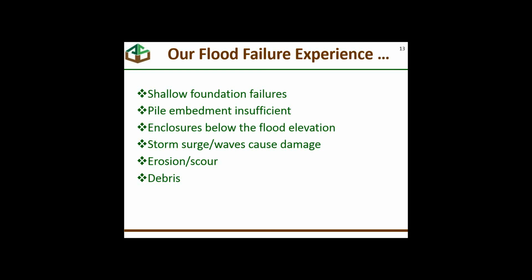There are enclosures below the flood elevation that can add load to the foundation, and those enclosures have to be well thought about. And in fact, many enclosures are not permitted by the National Flood Insurance Program for that very reason. So designers have to know what they can and cannot do below the flood elevation.